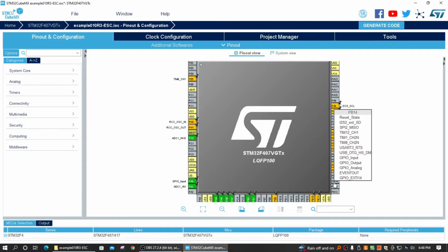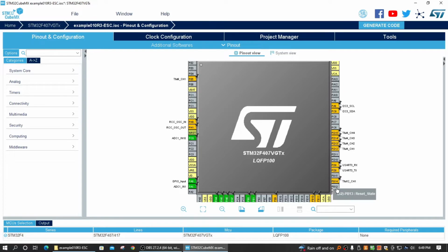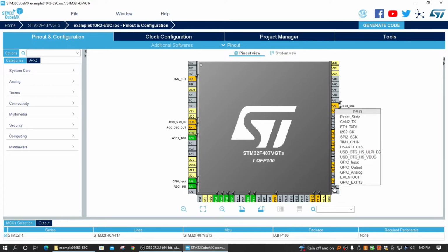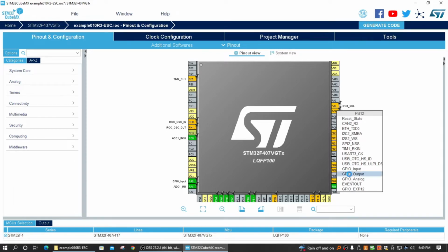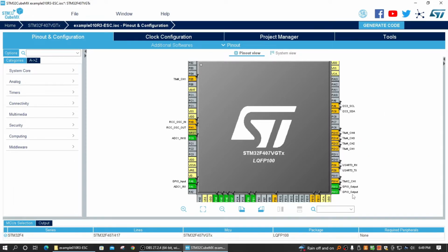Okay, so now we have timer 12, and this is for our servo simulator. And I have some general purpose outputs. I just use these to strobe. I look at it on the oscilloscope to verify that my update rate is good. This has a minor frame of 500 hertz, so pretty fast. I could get a lot of instructions, and this one is a 500 hertz update, and I'd let this one be a lower, a 20 hertz update.